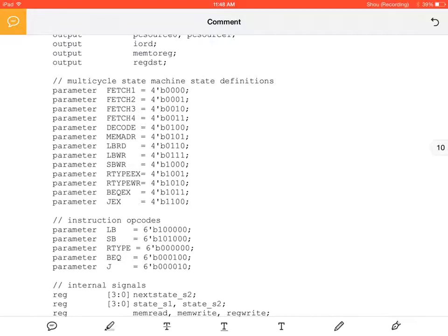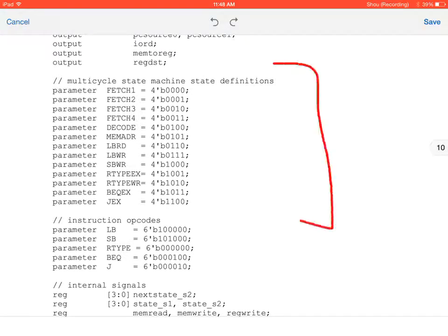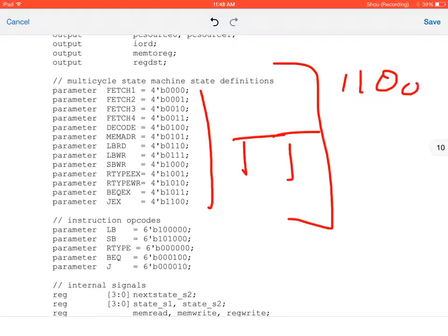So these are the current states that you have. As you can see, these values here pertain to your truth table. This is why doing the truth table is important, other than just doing busy work. You should know what the values are. So if we went through 1100 and we initialized our defined state as 1101, what do we need to do here